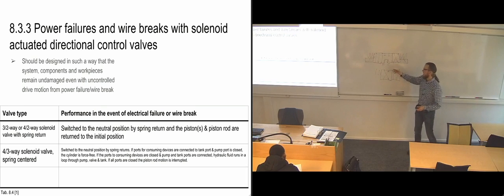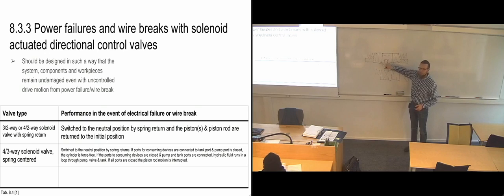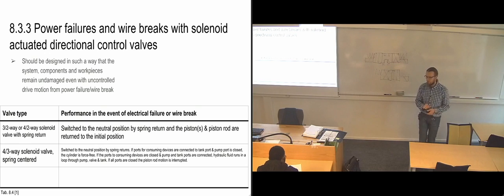So it's basically, if we disregard the resistance that we are going to get from the pipes and throttling points in the system, then you're basically going to have 0 bars of pressure going past here. You will always have something, because there is always a little bit of resistance in the system itself, but you definitely won't have 320 bars just being pushed straight into the valve and just staying there. It's just going to go in a circle instead.